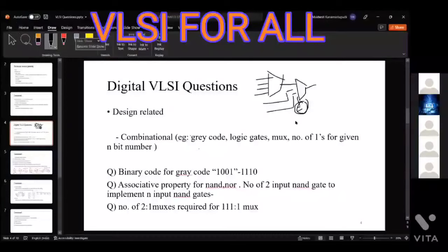Sir, in this we need 3 selection lines now. One can be used as an enable, taking 4 by 1 muxes with 1 as an enable. We are connecting 6 inputs, sir. For the last 2 we can make them ground. Can we do it like that? You are saying total 4 select lines now? 3 selection lines, sir.